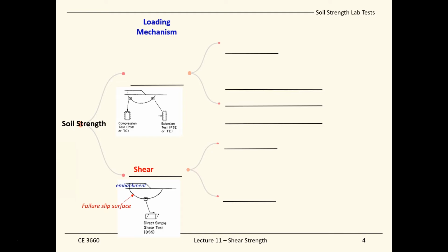for example, you have extension type of loading, which gives us the loading mechanisms that can be handled by the triaxial test. A triaxial test is like the compression test that you have done for your material mechanics class, where you have a cylinder type of specimen. You can do either compression or tension testing. But in geotechnical engineering, we call it the triaxial test, which is a fundamental geotechnical engineering topic in our business, triaxial testing.